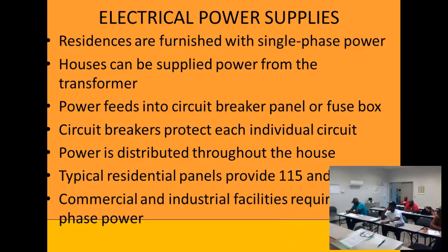Okay? And so when we measure these two wires, the difference, if they're coming into your house and it's 120, then the difference between the two would be 240. If it's 115, putting them together would be 230, if I can add right. But from here to ground, supposedly would be 120 or 125 or 115, whatever our supplier's given. But when we measure across this 90-degree angle, that's what we got.